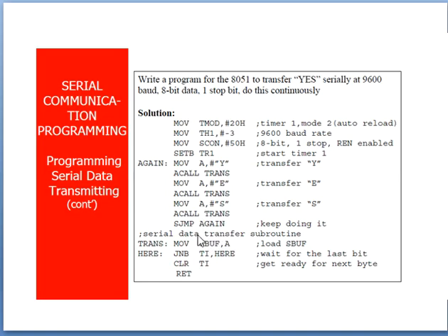And once RET is executed, it is going to go for the next instruction, that is MOV A, #'S'. So here it is going to call TRANS, in the sense again we are going to execute this. So all the bits of the S character will be loaded successfully into the SBUF register. Once it is loaded, again we are going to go for this, and it is going to execute continuously. So this is how this program is going to be executed.